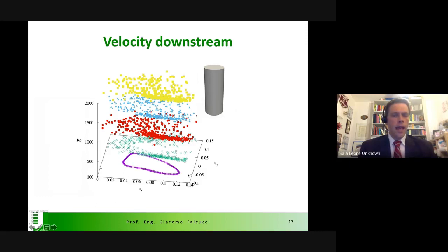You have an attractor-like, ordered structure for the velocity components until Reynolds 100. Then this order is already broken at 500, and it is completely irreversible: turbulence rises, and the velocity components are completely a mess for the different Reynolds numbers 1000, 1500, and 2000.